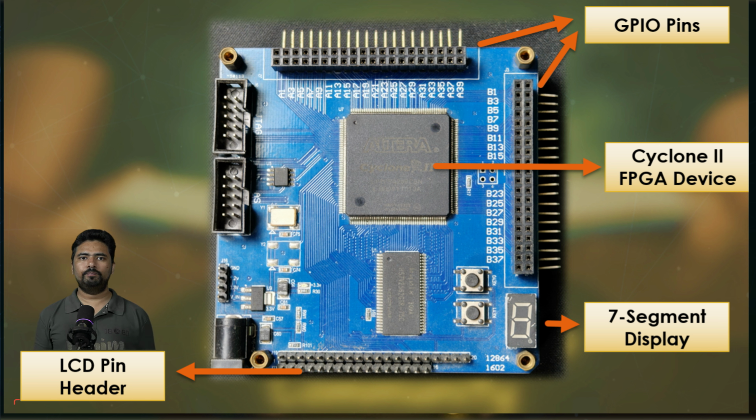final project. We will write test benches at the module level for the various modules and ultimately design a system-level test bench to ensure the entire system functions correctly when all the models and all the modules are integrated. We will use the wave window in ModelSim to analyze our results and ensure that they are aligned with our expectations. This approach ensures that our FPGA designs are thoroughly tested and function as intended.